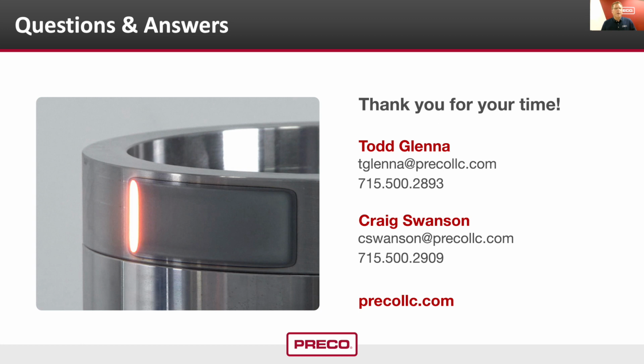Another question here, does the feature needed heat treating need line of sight for the laser? I'll let Craig probably respond to that one. Yeah, it does. It's a light beam. So we need access from our laser heat treating head to the surface that needs the actual heat treat. That is what is required. We will have instances where that feature may be hidden, and if we can't have line of sight to it, we're not able to do it with the laser.